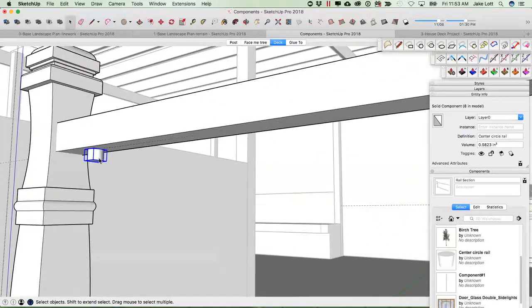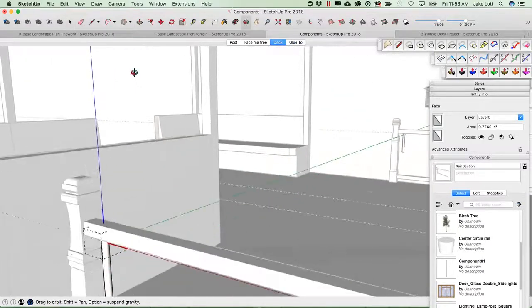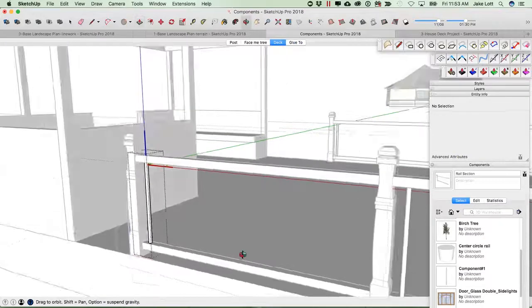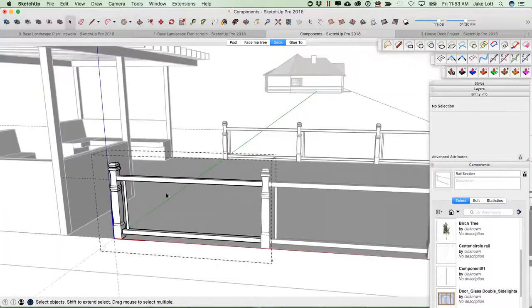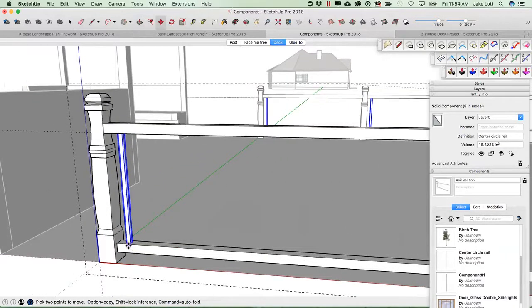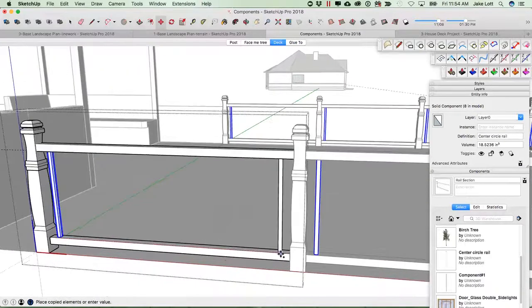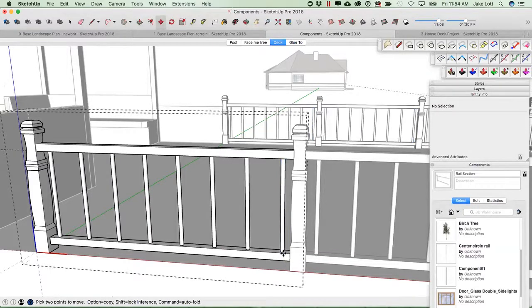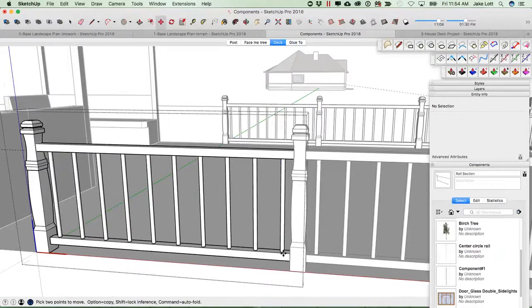And so then we can just double click into him and push pull him the rest of the way down and connect him in. So you can see I've got one of each of those in each one of those guys here. But I can also select him. We'll do that same move trick, make a copy, but I'm going to put it at the other end, kind of where I want it to end. And then instead of multiplying it, I'm going to divide it. So I'm going to do 7 divide, and you can see that it puts in 7 equally spaced ones. Maybe it's 8 divide. And I can start playing with how close I want those. Obviously, if there's a specific distance, then we would follow those standards.